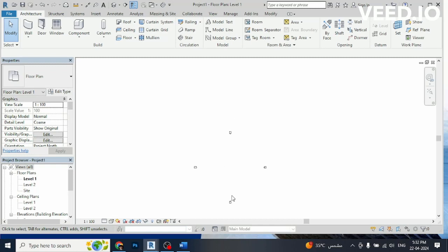You can see the main preview in the center, several panels on the left and the ribbon bar on the top, collecting all editing and drawing tools. While the main architectural tools which we are going to use in our project you can find under the Architecture button in the Build section. All these buttons collect multiple tools under the arrow button, so you can check details by clicking over it.